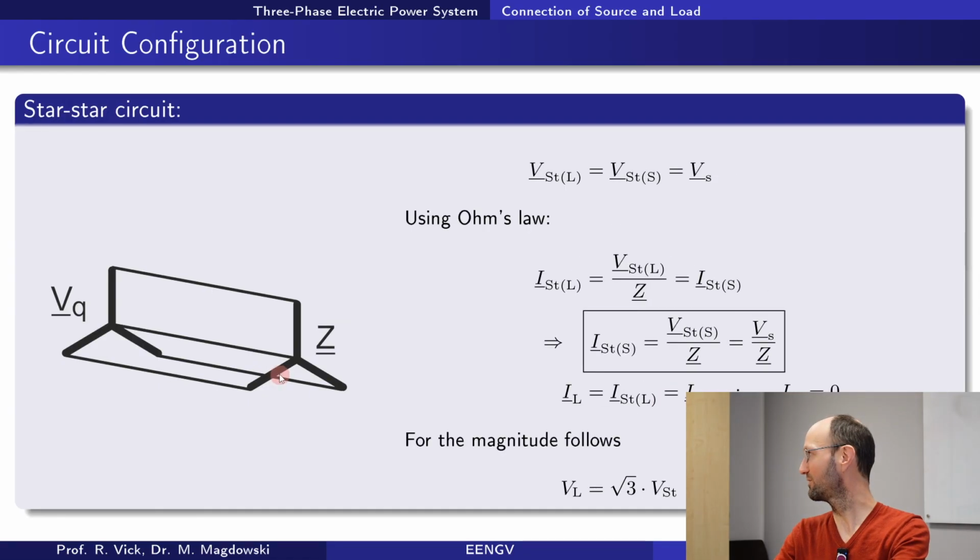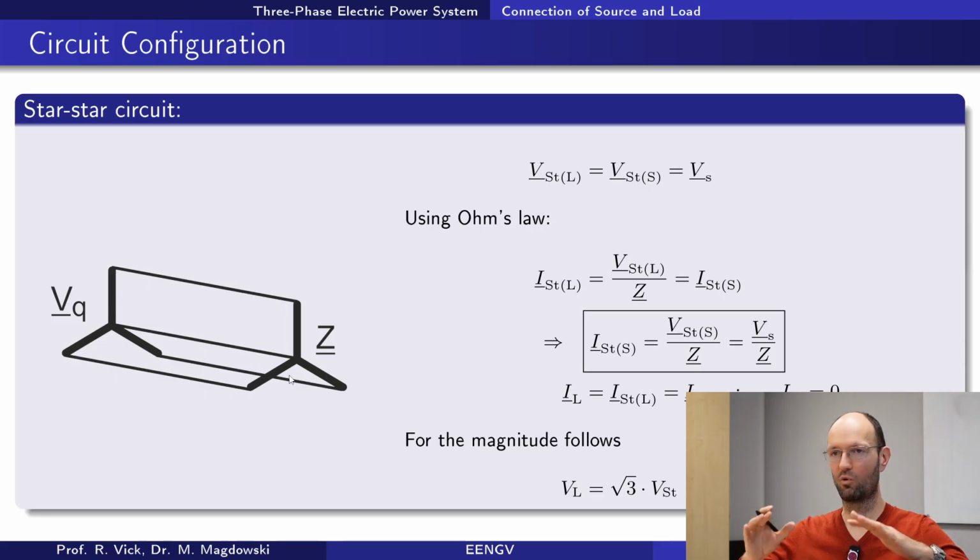Have you learned something like this in your vocational training, changing of motors? I'm not sure. Yeah, so to limit the inrush current of motors, you have a big and powerful motor and you directly connect it to the grid. At the beginning the motor needs to start to turn, so there's no counter voltage induced in the motor, and so the motor will draw a very large current from the mains grid. And this will lower the voltage, and it might trigger the fuse and so on. So this is also one option.